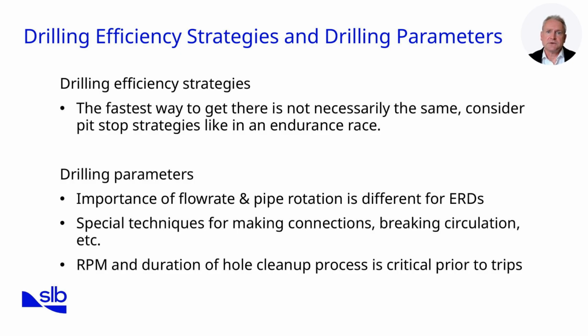Skipping this step often leads to back reaming or extended downtime later. So, in ERD, success comes from disciplined parameter management rather than sheer ROP. From here, let's examine how we monitor hole conditions to ensure stability.